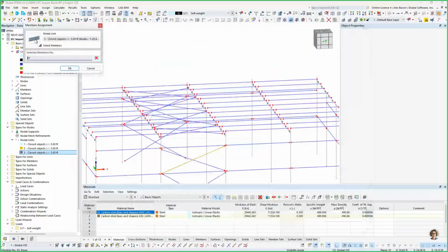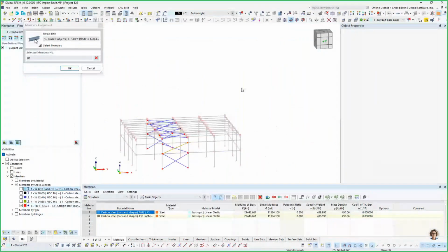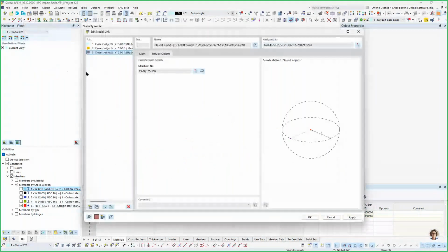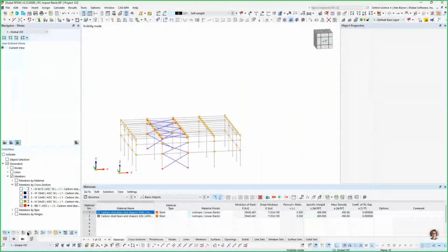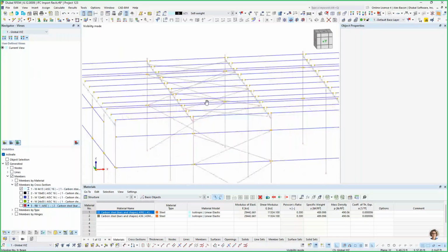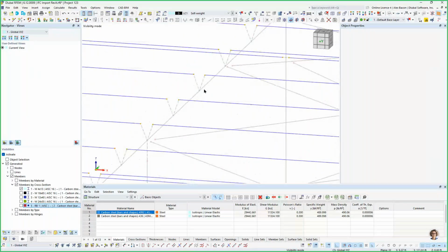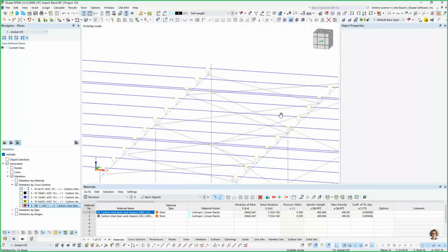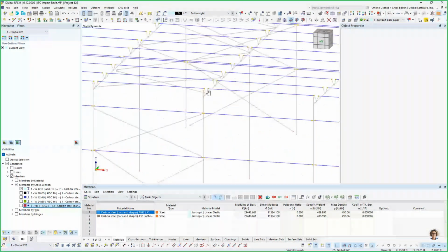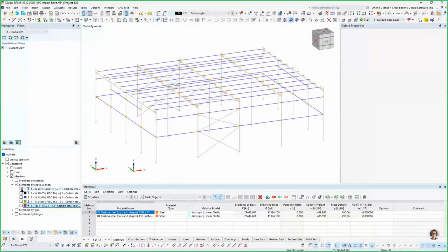being selected. So I'm just going to choose all of my X bracing to exclude from that nodal link. And yeah, so let's double check. So yeah, all of my coupling members are now connected to my center beams here with that eccentricity and no longer connected to any of the cross bracing. So that's good. And next, we want to do the cross bracing.